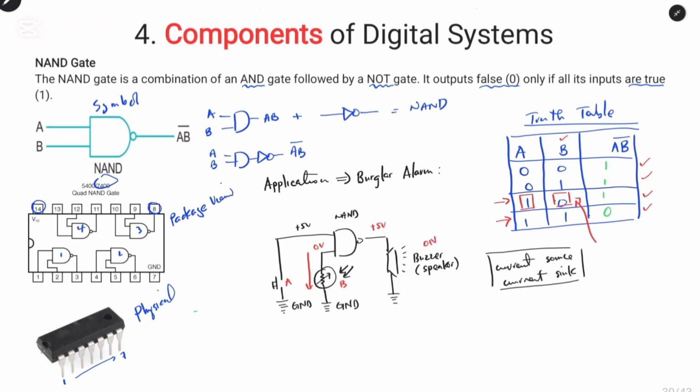The important thing to understand in this circuit is how to achieve a potential of 0. To achieve this state, we won't do anything with switch A, maintaining the 5 volts at input A, which is high. We only have to apply light to the light-dependent resistor, and this light-dependent resistor will be switched on, allowing the 5 volts to be grounded.